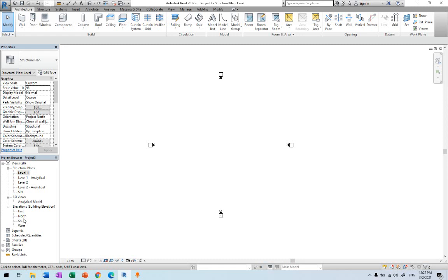But mainly you draw things in between them so that when you go to these elevations, you will see the building from the outside. So elevation, the name itself, means looking at the building from the outside. The building has 4 sides, so we will have 4 elevations there. We can add more if you want. We'll come back to them. That's something else. But those are the elevations that we have here. So when you draw things inside here, we can look at them in the elevation.